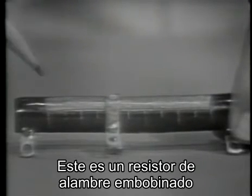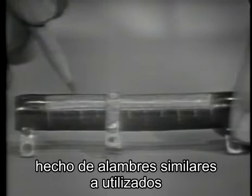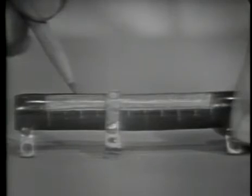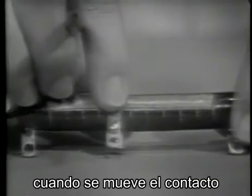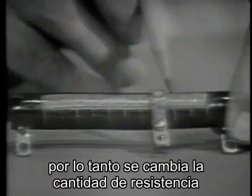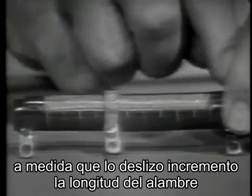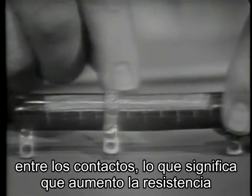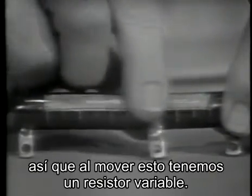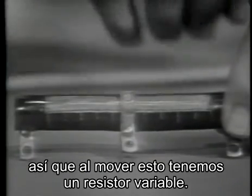This one is a wire-wound fixed resistor with a variable sleeve. It's made of wire very similar to the wire that we used in the demonstration earlier. By moving this sleeve, we can change the length of the wire, say from this contact to this one, thereby changing the amount of resistance. As I slide the sleeve down, I increase the length of the wire, which means that I have changed the resistance from this terminal to this one. So by moving this, we would have a variable resistor, wire wound.